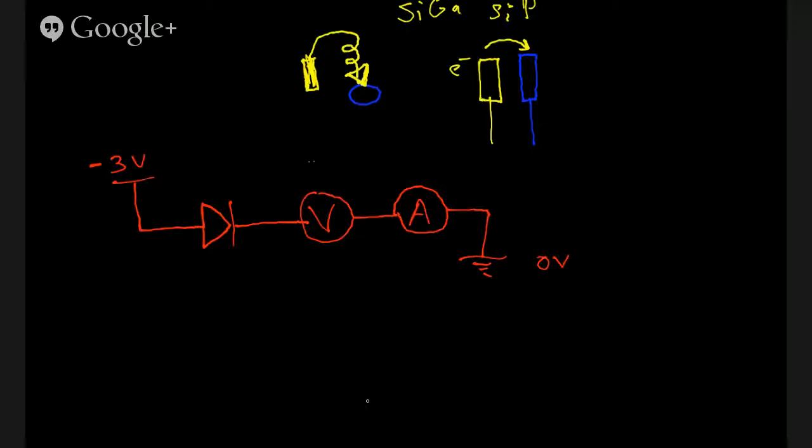The voltage we'd read here would be 0 volts, and we wouldn't get any current either, because, remember, a diode only conducts in one direction. Because our current would be reversed, this is the higher potential, our current would go this way, and it would be blocked by this diode. And if we turn this around and make this end our anode, and this is our cathode,